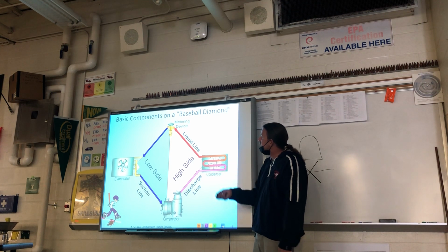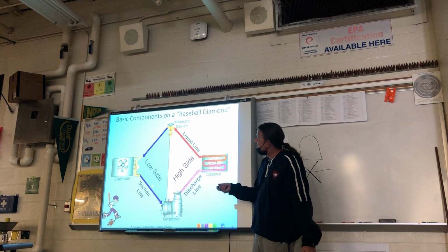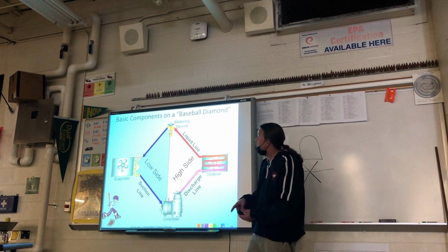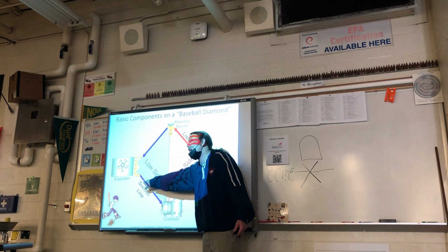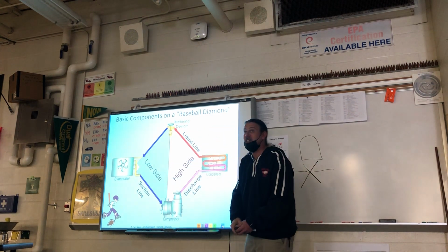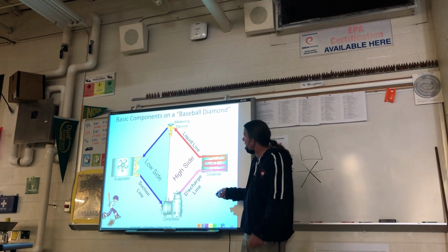So which of these lines would be the coldest then? Suction. Out of the three, yes, the suction line is coldest, but this is actually a little bit cooler because by the time you get here, it's superheated vapor, and that was all 40-degree liquid with R22 feeding into it. We don't have that line listed, but yes, you are right. The hottest line is the discharge.